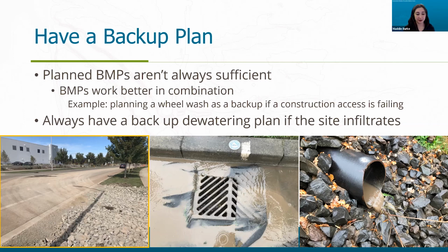But then here you can see in the second picture, it ended up raining. And although they have the witch's hat in there, turbid water was discharged into a nearby stormwater pond. And so these contractors were required to clean out the catch basin, clean up the site, and they ended up pausing work for a while to get everything in order. So it's great to have a backup plan for when the BMPs listed aren't quite sufficient.